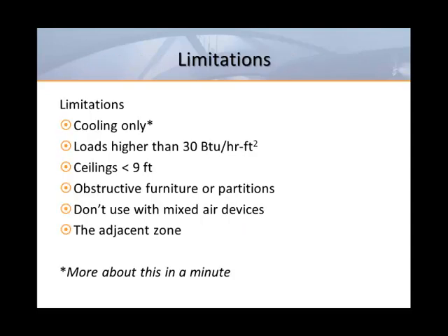So we've covered the advantages, but now we have to look at the limitations. From their design, it's easy to see why displacement diffusers are not generally suitable for heating applications. Slow-moving hot air would simply rise straight to the return without providing any circulation in the room. There is, however, an interesting solution to this problem, and we'll get to it shortly.